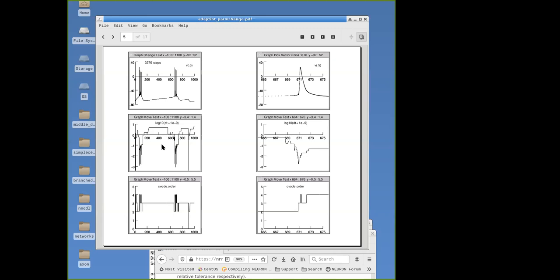Well, we'll talk about that in a minute. But notice the point here is that the adaptive integrator does adjust the time steps, and 0 means 1 millisecond, 1 means 10 milliseconds, -3 means 1 microsecond. And you'll notice right here, at a time that corresponds to the very end of the injected current, there's a sudden drop down to a very small value, okay?